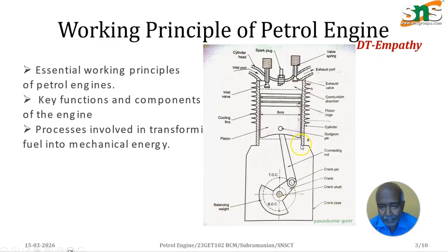After the mixture has entered into the cylinder, the piston moves from the bottom dead center to the top dead center, from BDC to TDC. That is, the piston moves from B to A. It compresses the air-fuel mixture inside the cylinder, which in turn burns and releases heat energy, ignited through the spark plug.